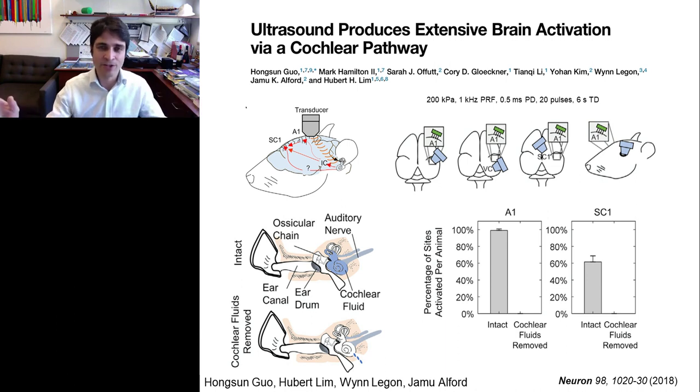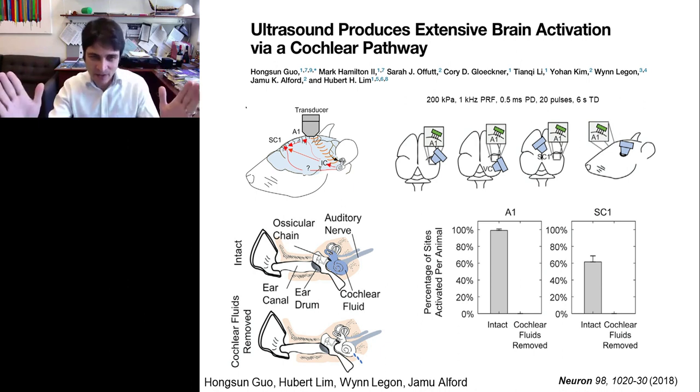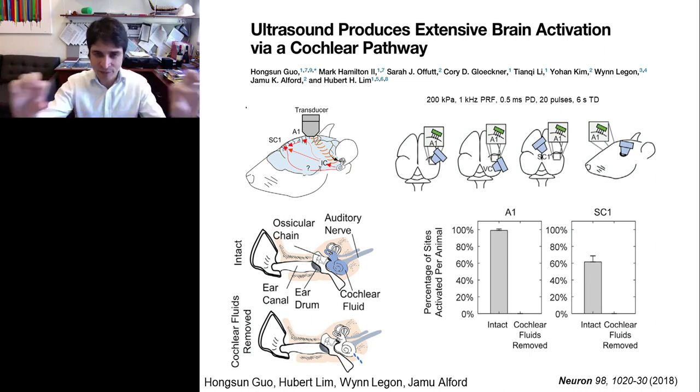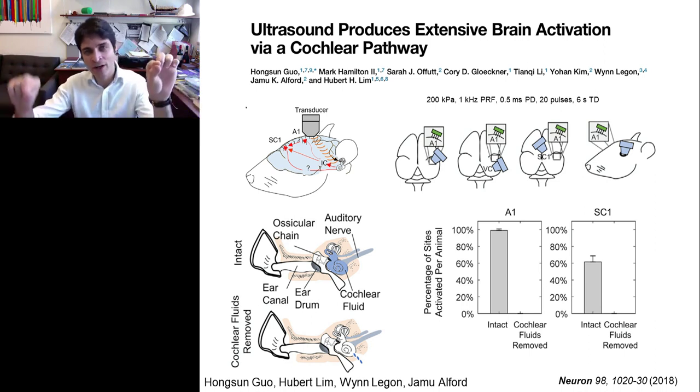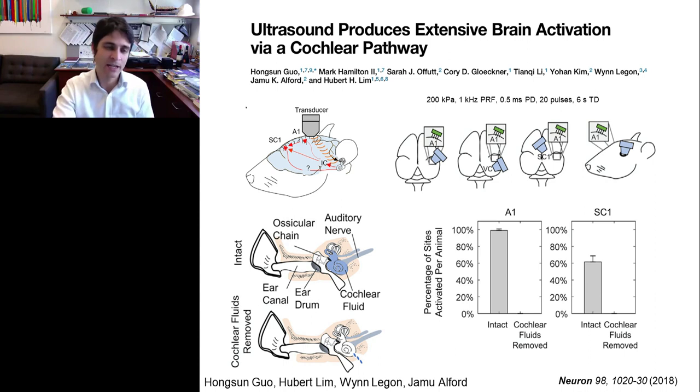And so if you take a Fourier transform of that waveform, then you're going to see not just your ultrasound frequency, but also the pulse repetition frequency, which could cause these auditory effects. And even if you are creating a continuous wave pattern that should be a pure tone, the abrupt turning on and turning off of that pattern can also lead to the generation of additional frequencies besides your pure tone frequency. And so that's something that we're trying to investigate to a greater depth, as I'll talk about in a few slides.